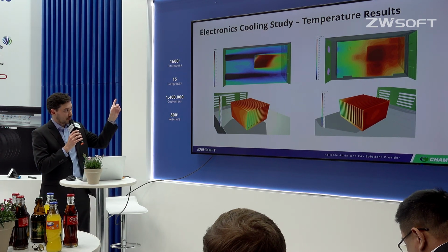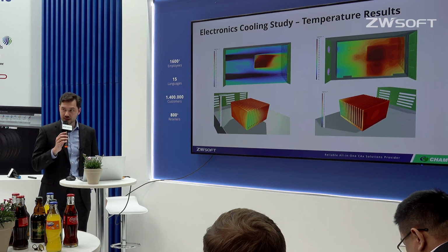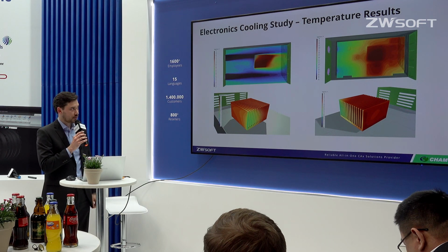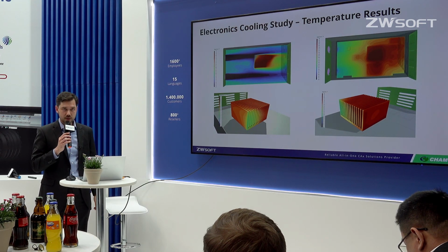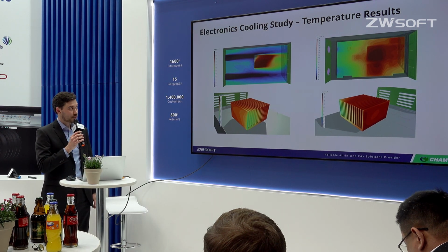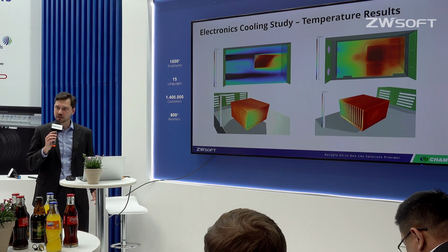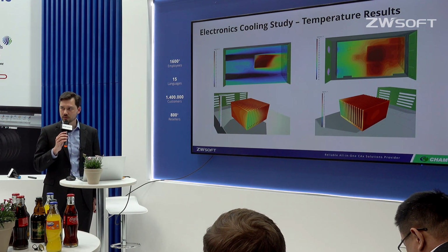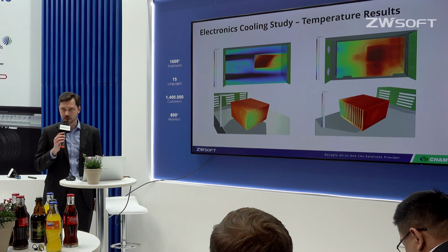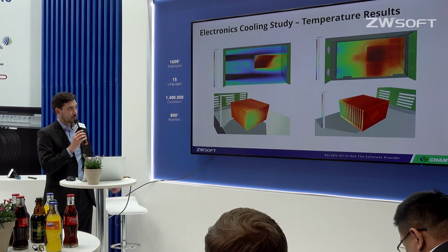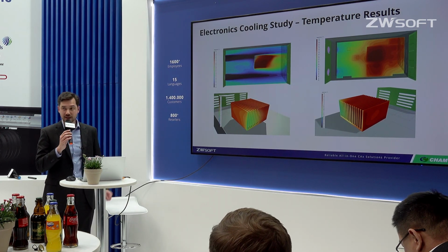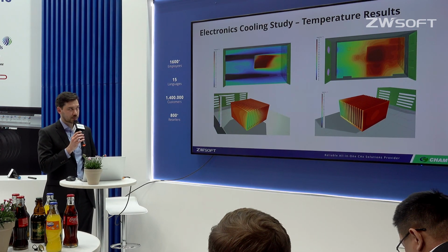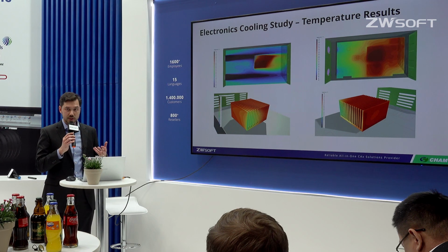So in the top left again, but this time I've hidden the heatsink geometry. We see the temperature. The temperature reaches 94 degrees, which for electronics is still acceptable, but typically systems like to operate below 65 degrees Celsius. We also see that most of the heatsink area is that dark red. This is significant because it means that there's a buildup of heat.